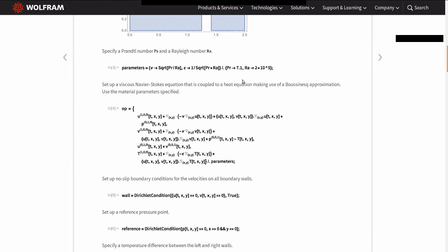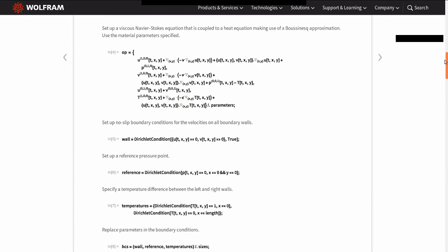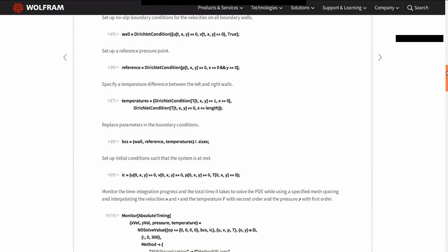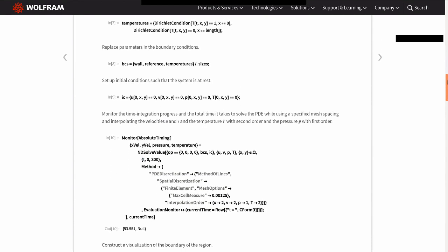This time, I didn't mention this before, but I've used a Reynolds averaged version of the Navier-Stokes equation. Previously, we just directly entered the parameters into the Navier-Stokes equation. There's no particular reason why I do this here. I just wanted to show that you can also do that. It's just a different way to set up the Navier-Stokes equation. Right, so boundary conditions: everything else is a wall. We have a heating and everything else is a wall. And initial condition, everything is at rest in the beginning.